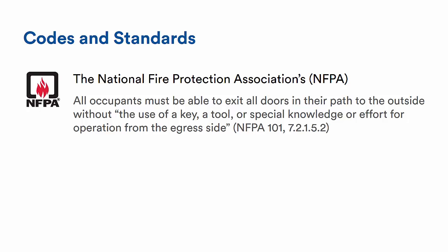or special knowledge. Of course, there are exceptions to that in the case of prisons, bank vaults, old folks' homes, and the newborn nursing floor of a hospital. In the case of a nursing floor, for example, in the hospital, typically a delayed egress device like a crash bar is used, where if a card isn't presented to exit, the individual would need to apply 5 pounds of force on the door for about 15 seconds, or say 30 seconds, before the door opens. During that time, an alarm will sound and operators will be notified.